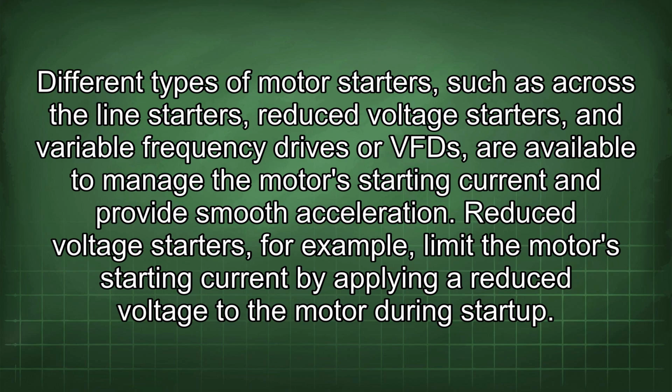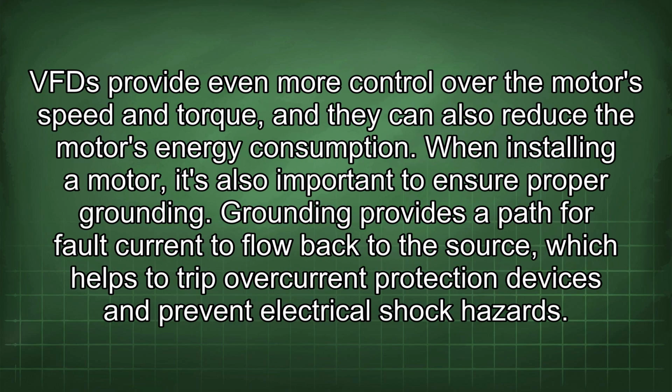Reduced voltage starters, for example, limit the motor's starting current by applying a reduced voltage to the motor during startup. VFDs provide even more control over the motor's speed and torque, and they can also reduce the motor's energy consumption.